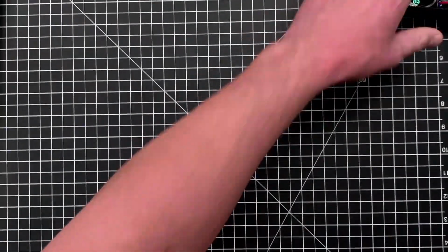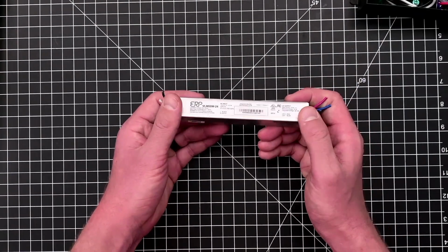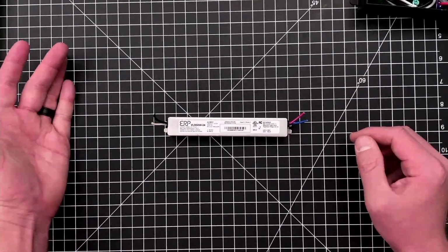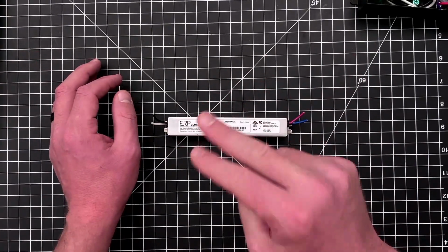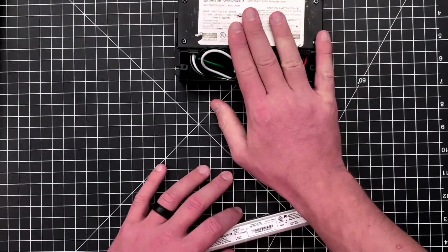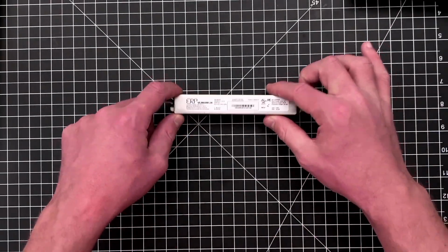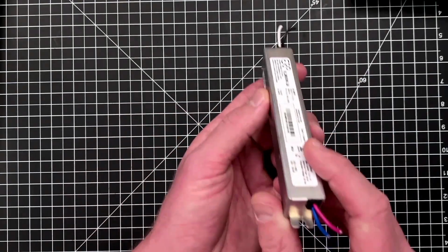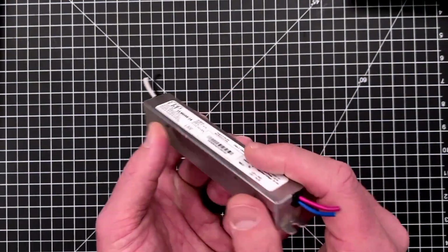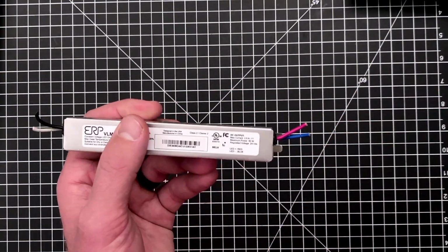And then this is what I suggest for everything that's color changing. So tunable white would be considered color changing since it's 3 wires. It's not our warm dim, which is only 2 wires. So for 2-wire warm dim, you could use our OmniDrive X, but for tunable white or color changing, I would use our VLM. And why I love our VLM, it's very, very low profile. It also just works. It's a great little driver.